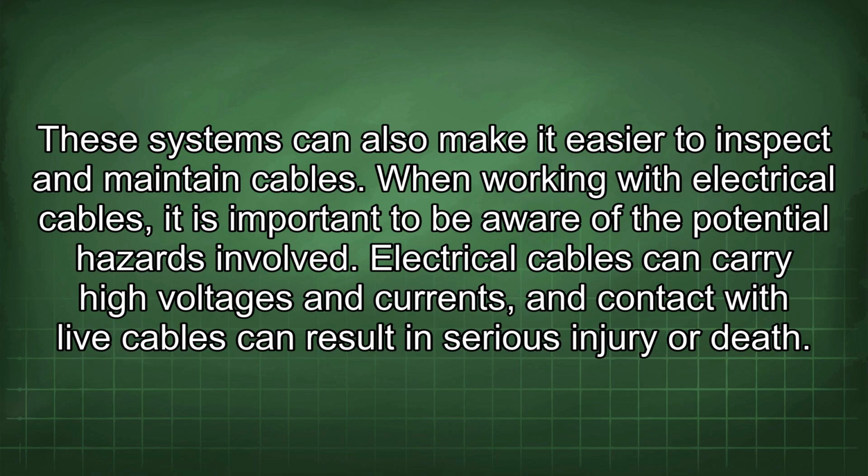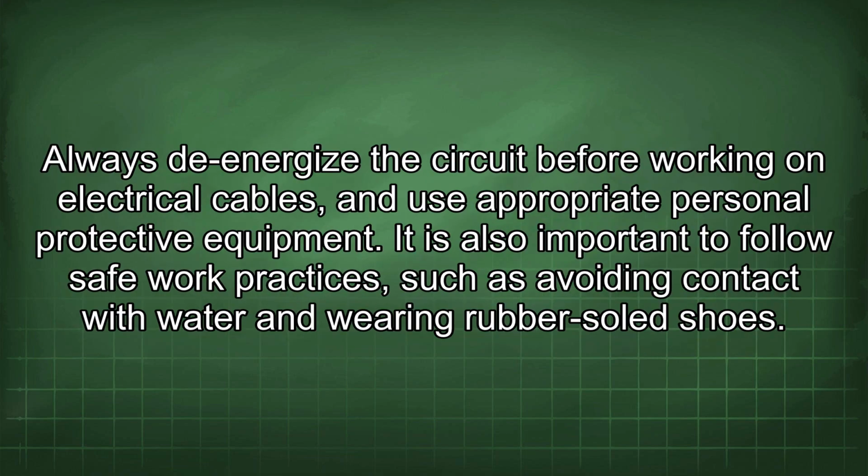When working with electrical cables, it is important to be aware of the potential hazards involved. Electrical cables can carry high voltages and currents, and contact with live cables can result in serious injury or death. Always de-energize the circuit before working on electrical cables and use appropriate personal protective equipment. It is also important to follow safe work practices, such as avoiding contact with water and wearing rubber-soled shoes.